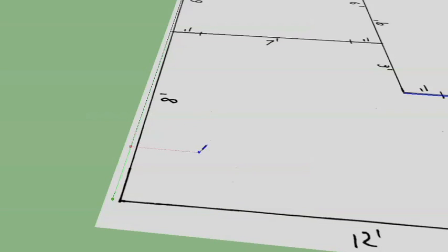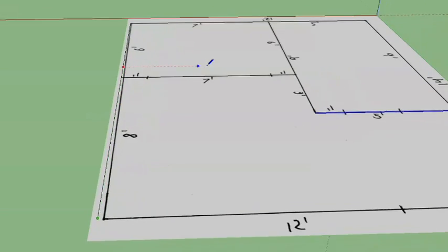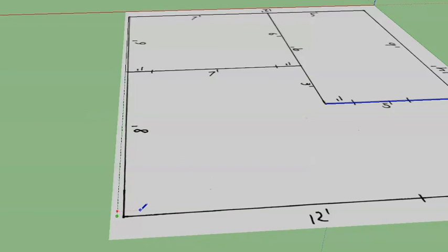There we go, perfect. And you can see, just as I thought, this particular wall was a little bit lopsided, so no big deal. Now it still wants me to keep drawing lines, but it's locked to the green axis. So to get it out of the green axis, I'm just going to hit the left arrow key again, and now I'm in freeform. I want this to go on the red axis this time, red and right, colors and directions, they kind of keep them nicely color coded, so I'm going to hit the right arrow key and that'll lock it into the red axis.